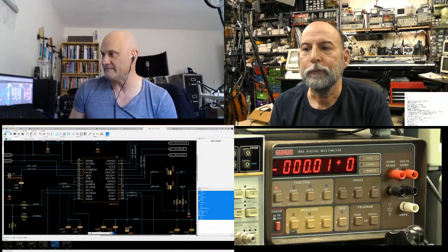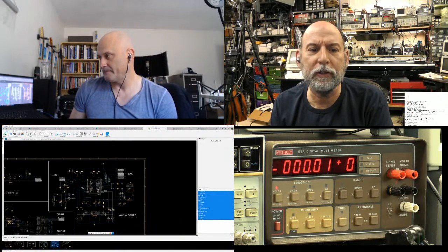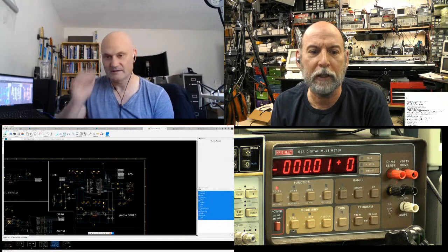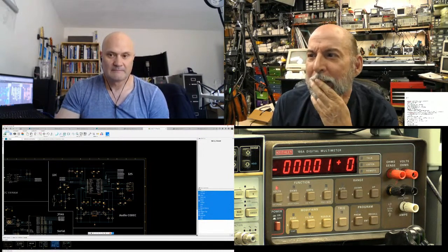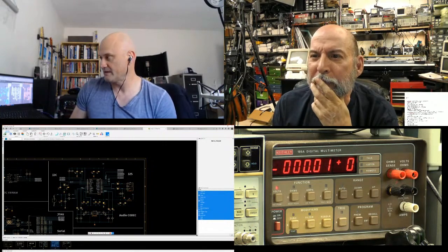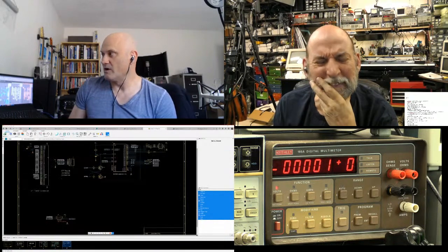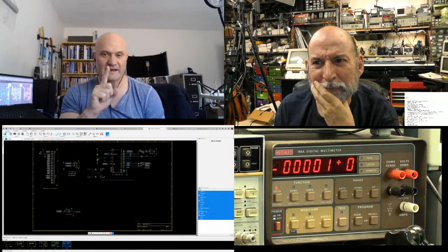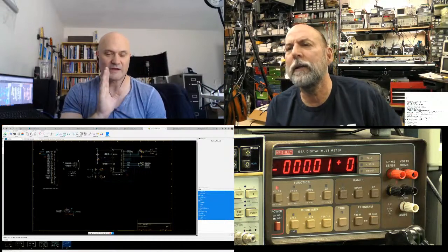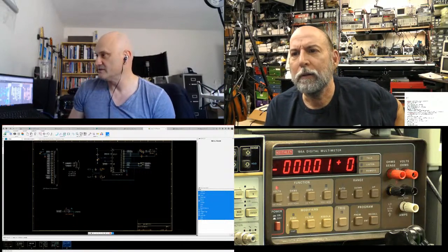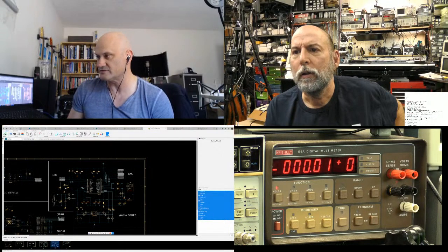So I got that done, and then... Would you call those different sample rates or different clock domains? Chris from the chat channel called it clock domains. Well, if it's a sample rate, that infers a buffering in the middle. Well, they share the same master clock, and everything is synchronous to the master clock. So it's one clock domain. And that's the master clock in this chip. It has its own master clock, which is this crystal here.